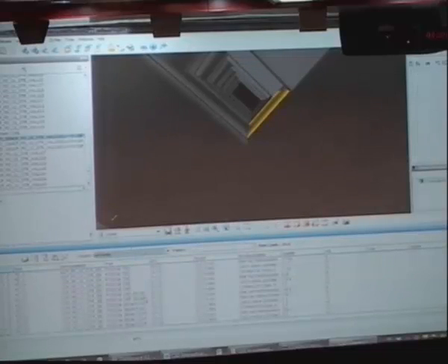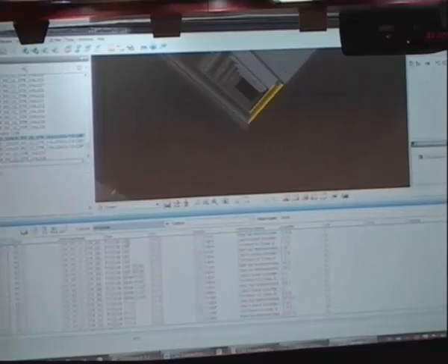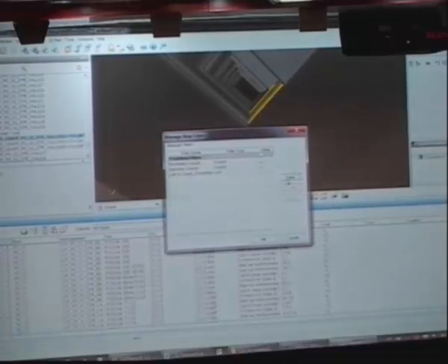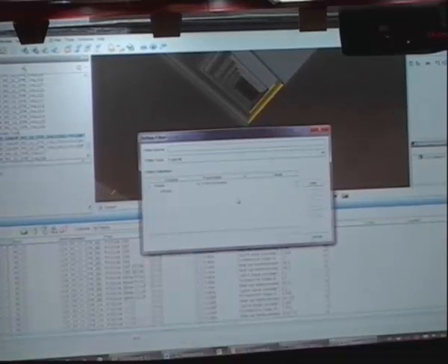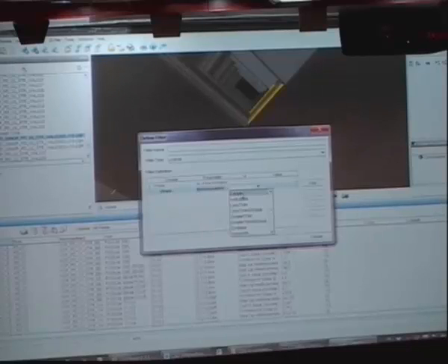Okay. So this iBox here contains all the material I have for everything loaded. And I'm going to choose a sample report. That's why the model is gray now. I'm going to send a report out to a subcontractor who needs to see what kind of objects need curved formwork. So I have everything here in my MTO iBox. I'm going to go ahead and make a filter. In C3D iBox, you have different types of filtering. You have the quick search where you can do a search on the fly, and you have more complex searches if you need to do AND or OR and different conditions. So let's take the BOQ description and we say curve.